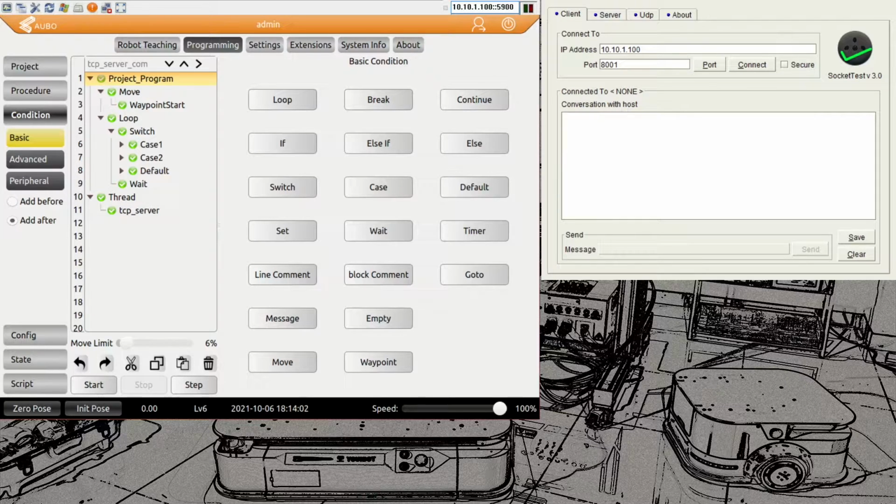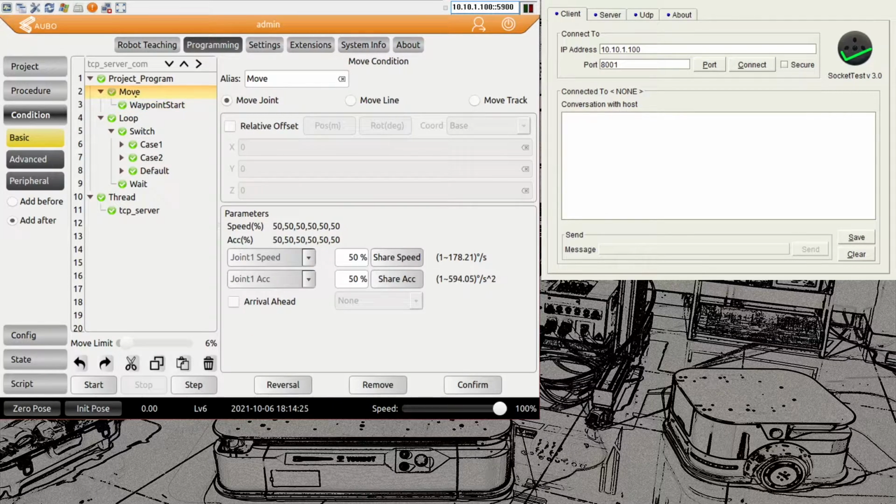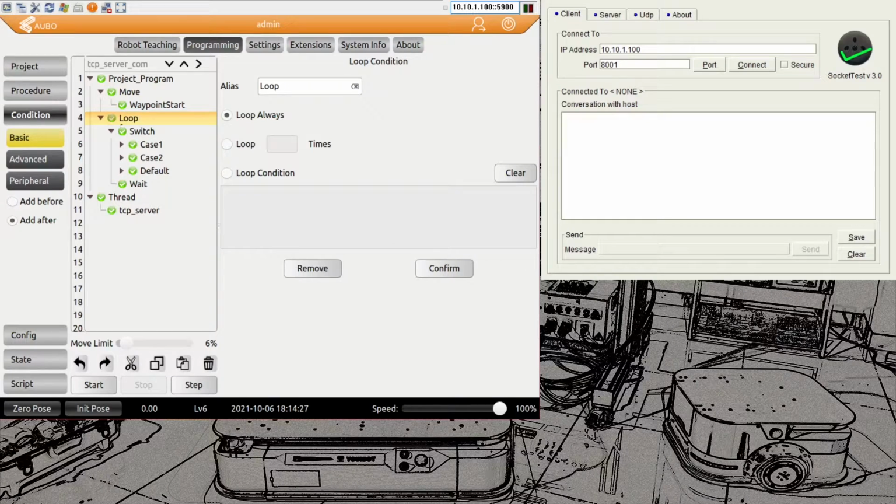First, I tend to do an independent move in the program at the beginning, because we need to define where the robot is supposed to start, and we manually have to drive it to this position. Let's look at this one. We use an I10 in this case, and this is the start position for the robot. Remember, the main program doesn't loop by itself. So my move will be executed at the beginning, and then I only have the main loop in the program. That is what's actually executed constantly, and not the move on the top.